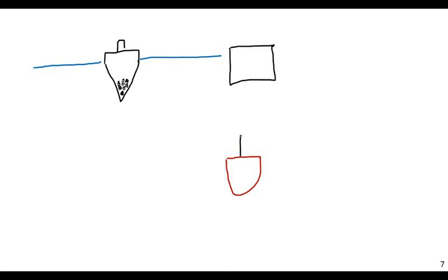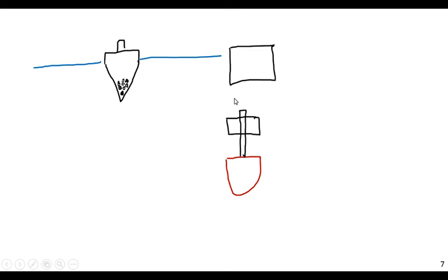In the days of wooden sailing ships, the only way the ship would propel itself would be to have large sails above the waterline. So that means you need a large amount of mass with a large moment arm high above the waterline. And of course, this tends to cause rotation. So they would tend to have quite a bit of ballast in them.